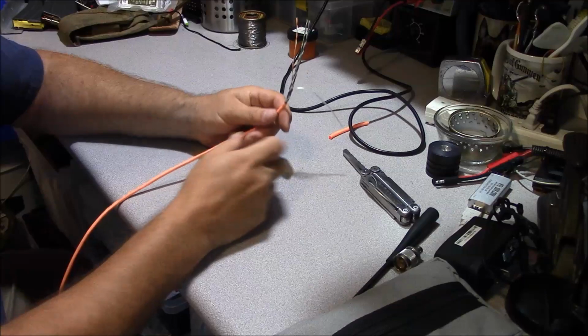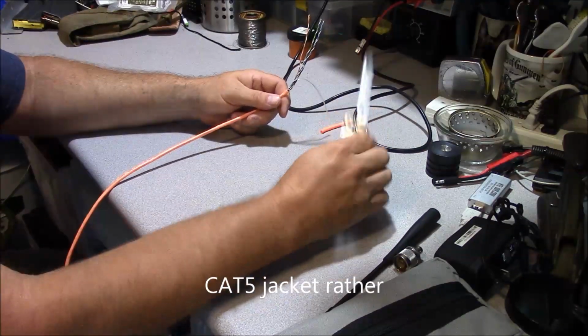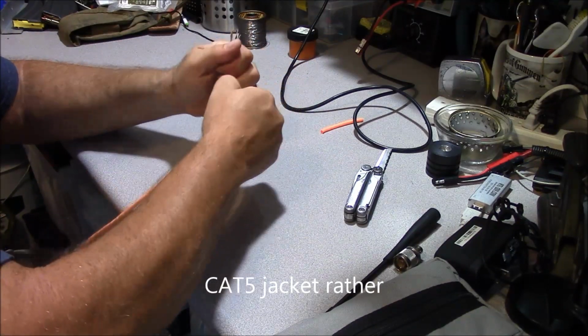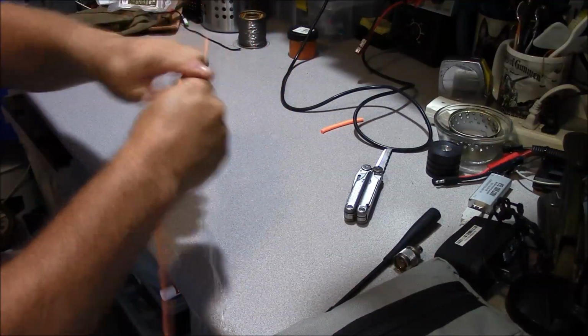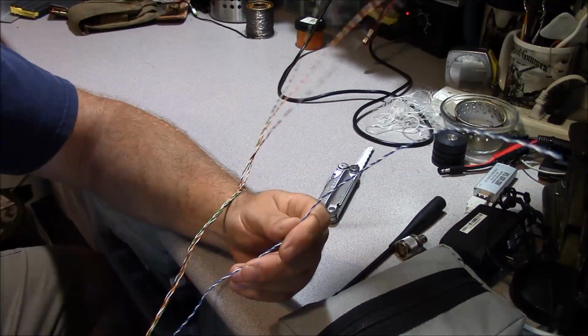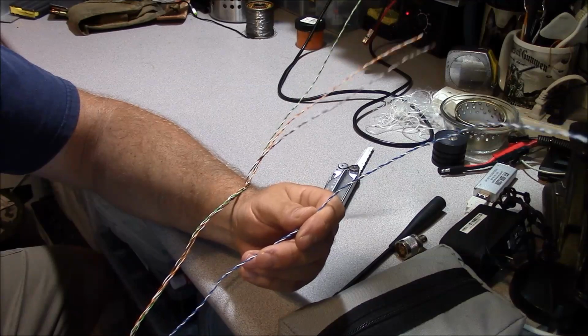Now we're going to go ahead and remove our Cat 5 cable. Just remove a few inches of insulation with your Leatherman tool, and then just grab a hold of that string and pull it. As you pull this string out, it strips away your jacket. So merely select a pair from your 4 pairs available, and that's going to be your feed line. Remove it from the bundle.